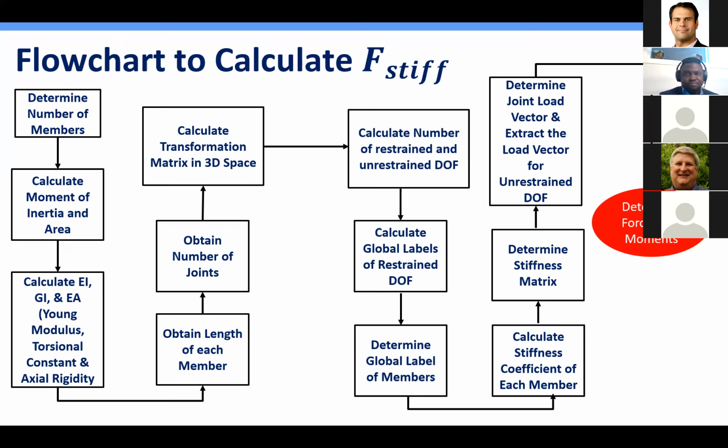And then if you have offset wells where you've done some post analysis, and you've done the stiff string modeling, and you pretty much have an idea of what friction factor you should be using, then you can play around with that. But like I said, the numbers don't lie. So if you go beyond the tensile and the buckling limit, then you're bound to face problems.